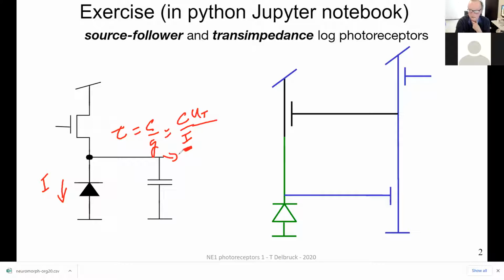So what about the output conductance of this device? Well, the output conductance, in other words, how strongly it can drive a load, is just this same GS, the GS looking up into this transistor. So if I make the current really small, it's going to be really, really weak. In other words, the lower the current, the weaker it is to drive something downstream, like some capacitive load.